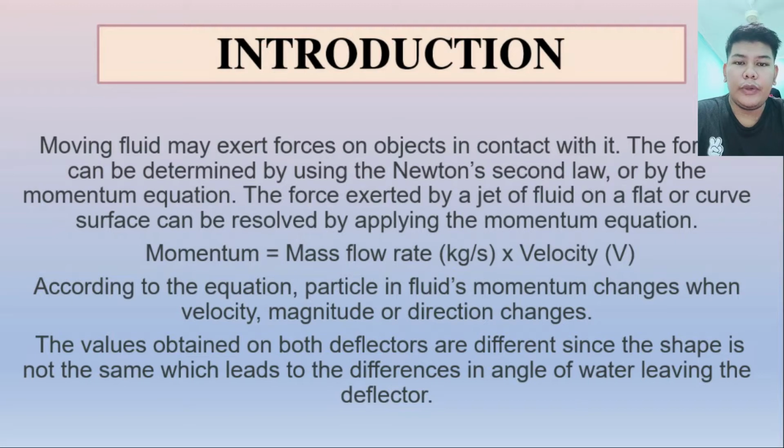According to the equation, particles in fluid change momentum when velocity, magnitude or direction change. The values obtained on both deflectors are different since the shapes are not the same, which leads to the difference in angle of water leaving the deflector.